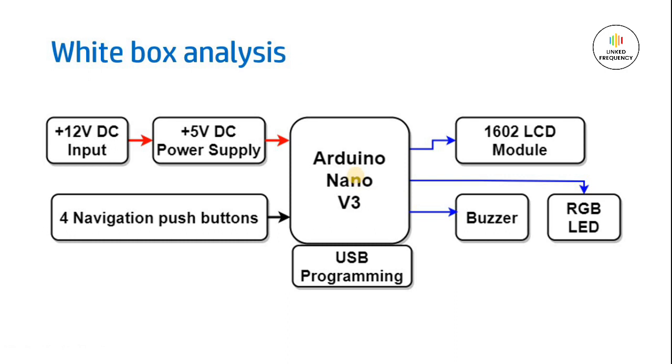Here we have a catch. The thing is, we have 2 types of LCD module in the industry. One is I2C LCD module, which is nothing but a normal LCD module. Along with that, there is an I2C module which we can solder to the general LCD module with 16 pins, and we can literally use that entire combination circuit as an I2C device with the I2C pins on the Arduino Nano development board, which is absolutely amazing, easy to use, easy to interface, and programming wise it doesn't make much difference to the development of the firmware or maybe the embedded application.